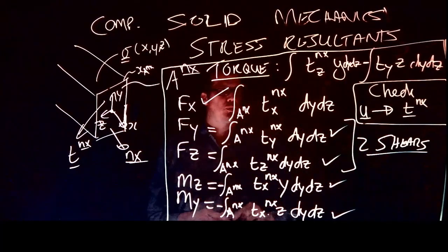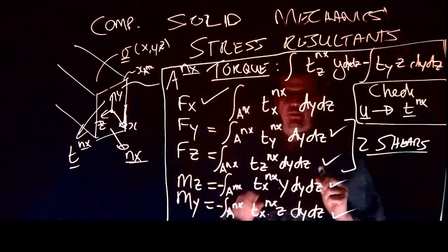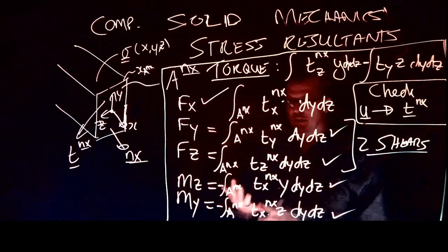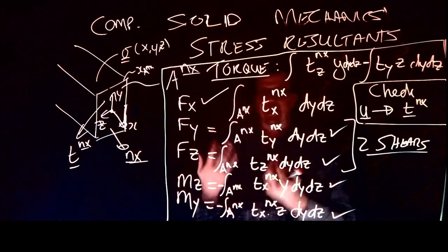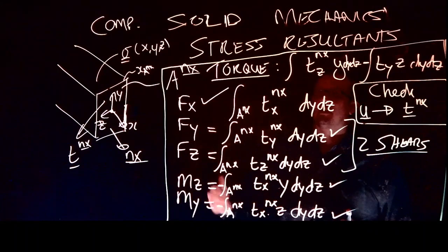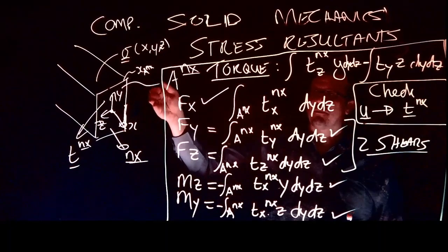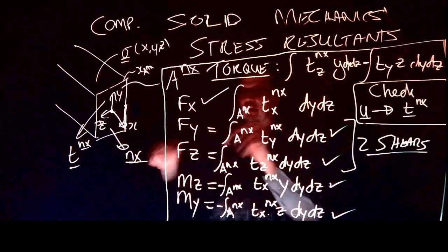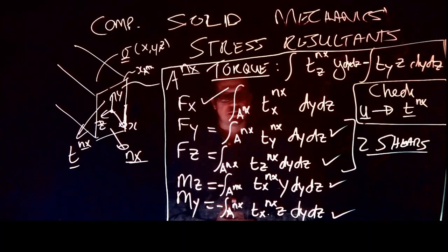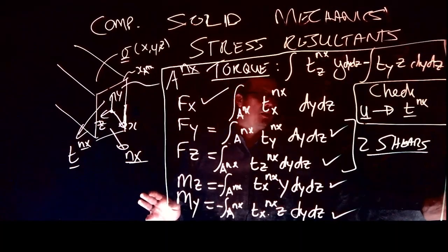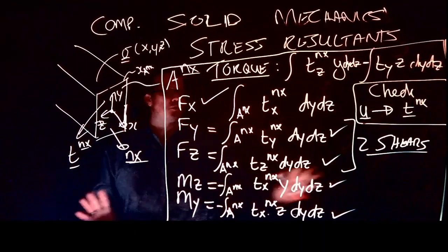And it is important that we are able to do that. Similarly, when I do a finite element method later on, we're going to apply loads and get a displacement solution, and FEM will allow us to see the stress field. But I can then take that stress field and check: what are the tractions, and what are the macroscopic stress resultants that follow on those surfaces? Are they what I expected them to be? That's the cool thing: we can go from macroscopic forces to a stress tensor, and then back from the stress tensor to the macroscopic forces. So this completes the check.